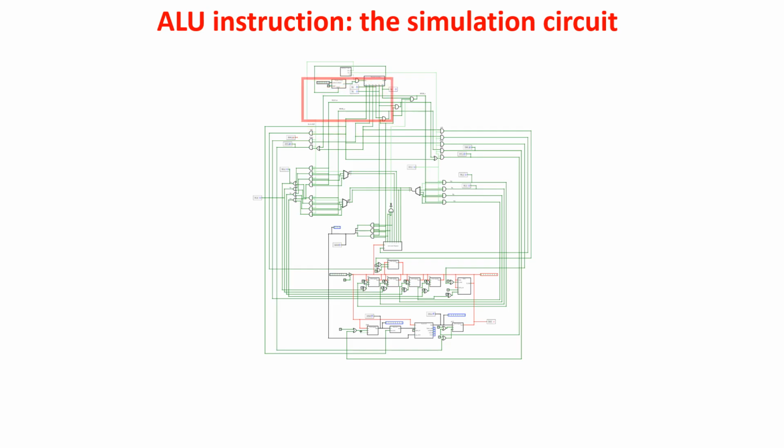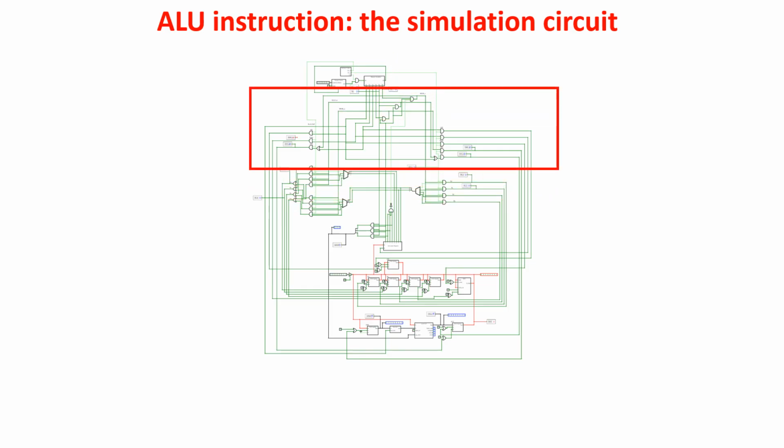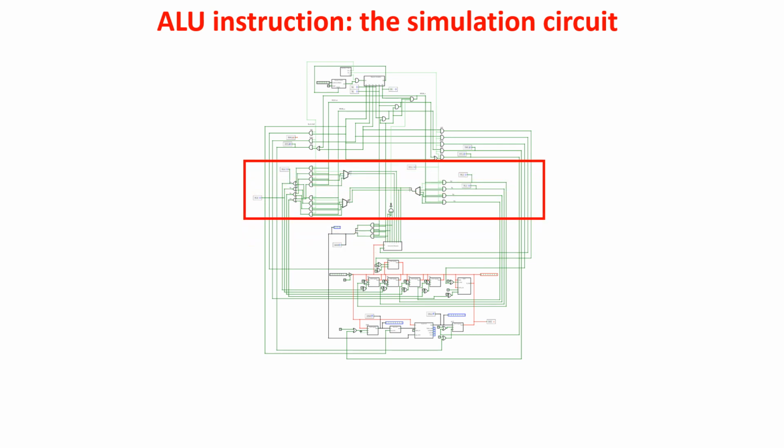Here we have the timing blocks, so the clock generator and the stepper. Here we use the timing blocks and the wires coming from the instruction register to give the enable and set pulses to the dedicated registers: the temporary registers, the accumulator, the memory address register, the instruction address register, and the instruction register. Here the logic to give the set and the enable pulses to the 4 registers from R0